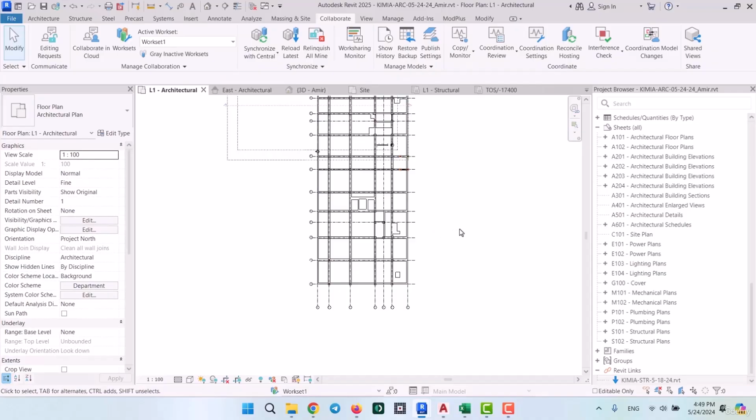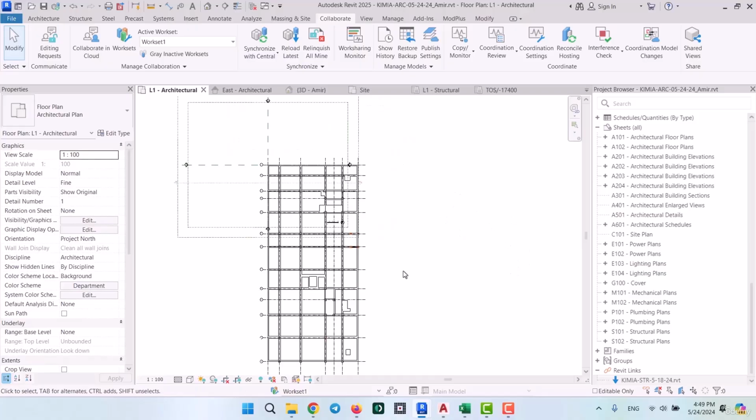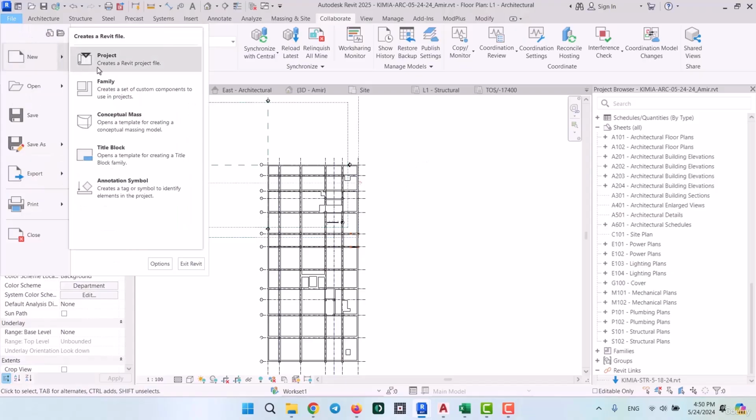Now you might think to yourself that this way you will have to go over to every single view and do that same thing over and over again. But here's a tip, you won't need to. You see, in all of our projects, we've got a view template. For example, for the measuring plans, we have one template, and another template for the flooring, and another template for the elevations. In fact, we have a separate template for each series of documents, which you could go into those templates and make your grids and levels invisible in there. That way you won't have to go into every single view, then to the Revit links to make the grids and levels invisible. And actually, I'm gonna give you a quick example to help you understand it better.